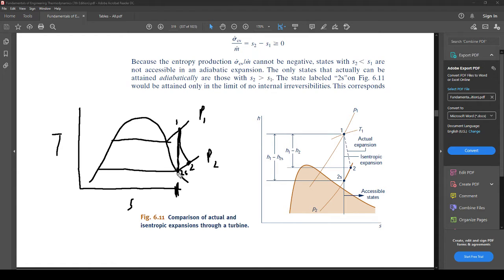So for example, I'm going to draw a Rankine cycle. This is the very first cycle in Thermo 2. So state 3 would be here, and then this right here would be state 4s. And right in between this process is a pump. In a Rankine cycle, it's a pump. So essentially state 4s, and then, as we've done in this example before, the actual one would be this way, because remember, it can't go the other way. So 4 actual would be that way. So this right here is a basic Rankine cycle, and it's only after a process like a pump or a turbine or something that you get an S. All right, so let's go ahead and move on.